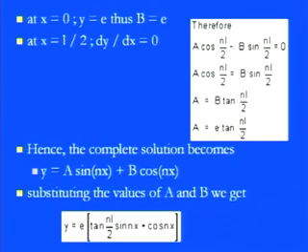So you see here we have the complete solution in terms of y equals a sin nx plus b cos nx. If we keep those values of a and b, we have the complete generalized solution of the equation in which the pin joints are there but the eccentricity is there. So eccentricity also plays a key role in the generalized solution. As you can see, in the equation y equals e times, this e is present exactly in the basic term of the solution.